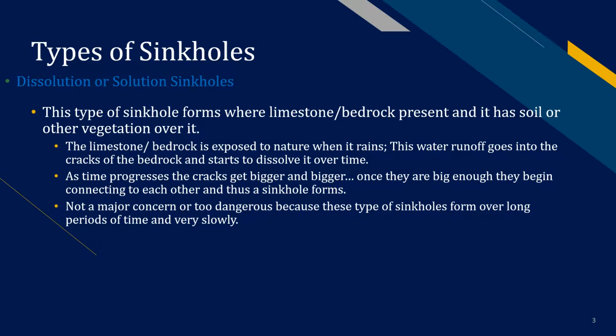Different types of sinkholes include dissolution or solution sinkholes. This is a type of sinkhole that forms where limestone is underneath the soil or vegetation over top of it. The limestone bedrock is exposed to nature when it rains, and the runoff goes in the cracks underground and dissolves it over time. This is going to take a very long time, very predictable, not a major concern for any type of construction or anything like that.